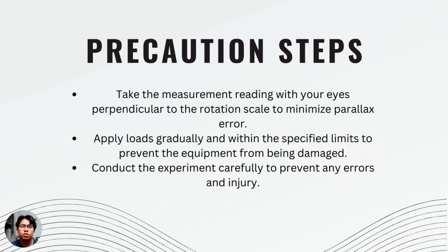For precaution steps, take the measurement reading with your eyes perpendicular to the rotation scale to minimize parallax error. Apply loads gradually and within the specified limits to prevent the equipment from being damaged. Conduct the experiment carefully to prevent any errors and injury.